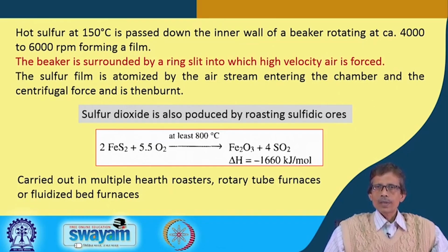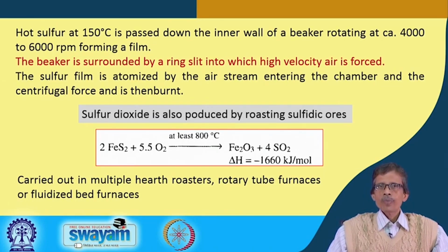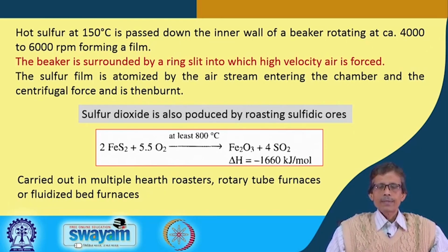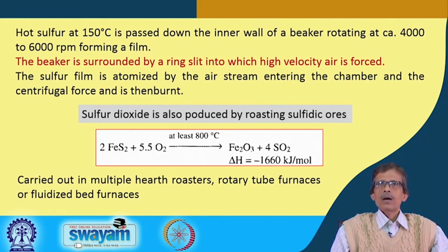But at the same time, we are also producing sulfur dioxide, and now we are focusing our attention on the other part, that means the production of SO2 from these ores, which will be utilized for sulfuric acid production. So, an industry focused on making iron and steel can have some byproduct of sulfur dioxide, and if they are careful enough not to dump that SO2 in the atmosphere, they can utilize it for the production of sulfuric acid. So, that industry will not only make iron or steel or any other material based on iron, but can also produce sulfuric acid from a very straightforward reaction of getting sulfur dioxide, converting it to sulfur trioxide, and that sulfur trioxide through water absorption giving you H2SO4.